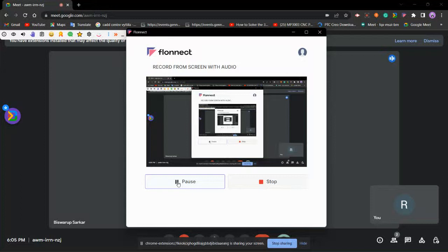The first tool, pad. You see all the removing operations are currently unavailable because there is no scope here. There is no body, right? First one is pad. While selecting pad, there are some sub options here, like in SolidWorks. The first one is type as dimension.